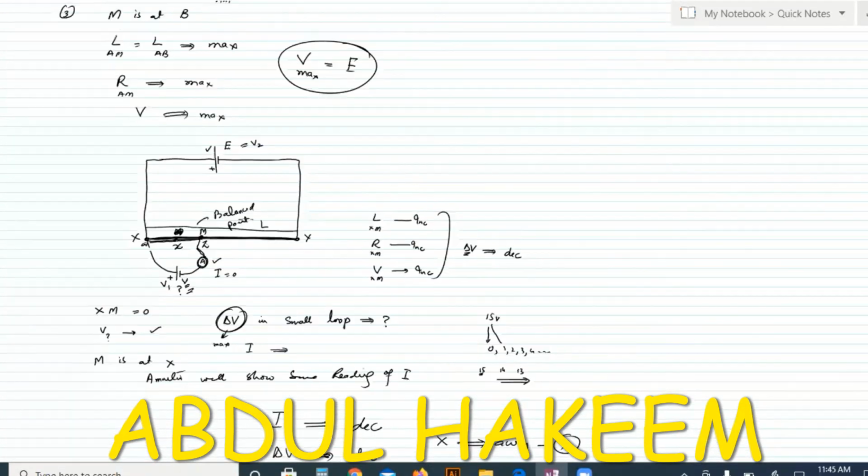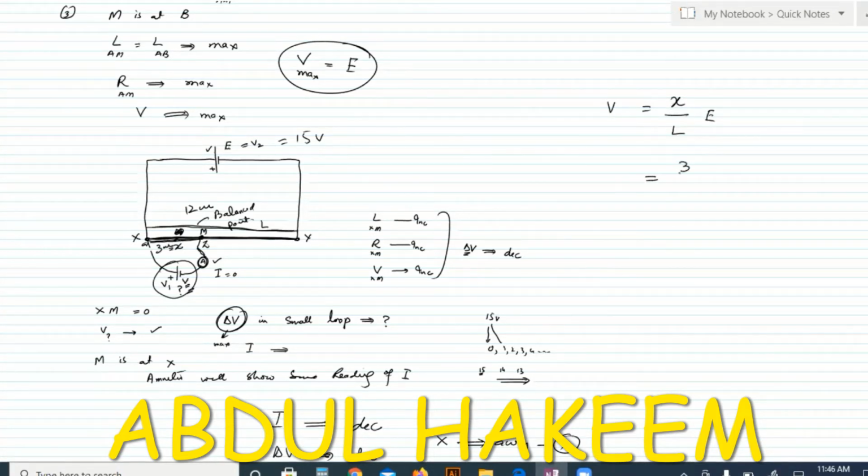For example, this known EMF is 15 volt, and this total length is, suppose, 12 centimeter. And this balanced point is coming at, suppose, the 3 centimeter mark. Then the question is, what is the potential of this cell? So the formula is V equal to X divided by L into EMF. So X is 3, L is 12, and the EMF is 15. So you will get the answer: 3 ones are 3, 3 fours are 12, so 15 by 4. This is the potential in volt for the unknown cell.